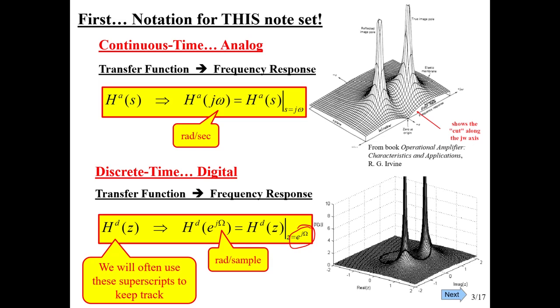And so it looks like this. That black curve there is the height of the magnitude. I say x here, but it really should be h. I just borrowed this from one of my other note sets somewhere. That is the magnitude of this h of z, this h superscript d of z, evaluated on the unit circle. So that's the frequency response shown on the circle, but we usually like to lay it out on an axis of omega.